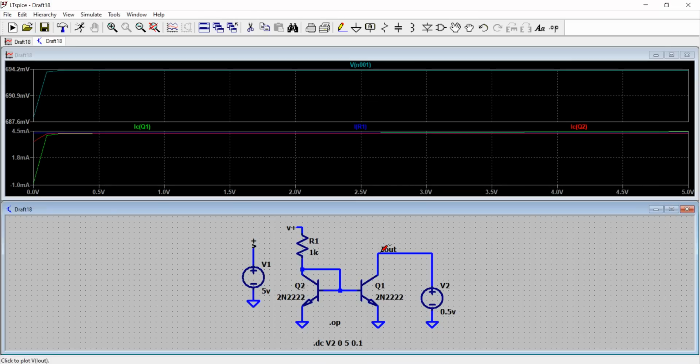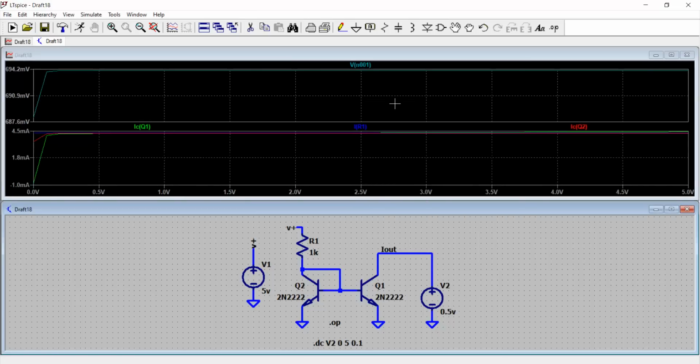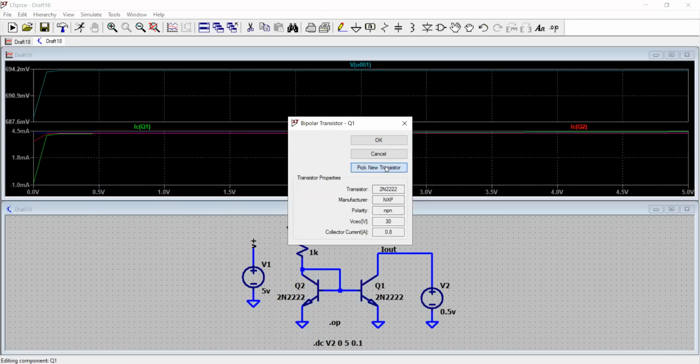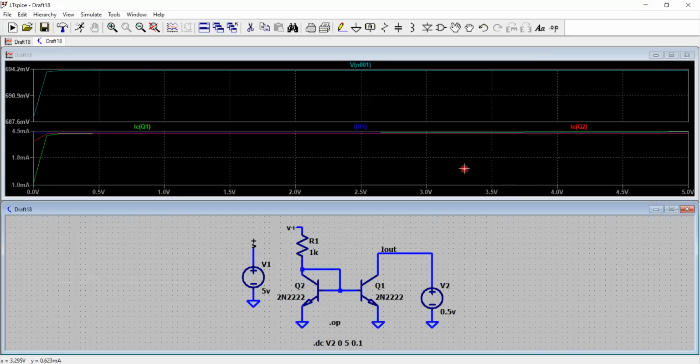And what is the voltage here? That is the voltage we are sweeping. So this is how you can simulate and design the current source, or actually the current mirror, which subsequently provides you a current source. Here for this transistor, you can see the transistor beta is 200, the DC current gain. So accordingly do your calculations for how you want to design for a specific current.